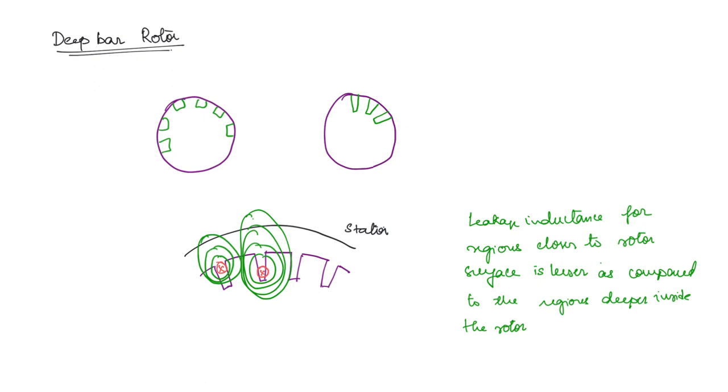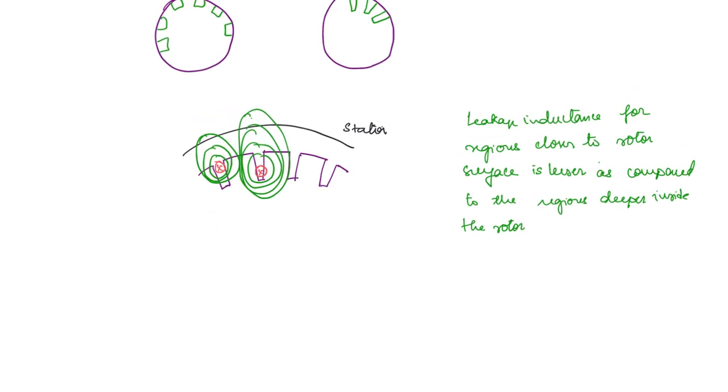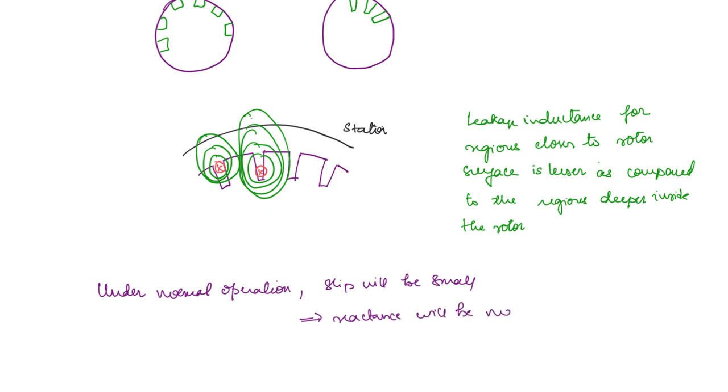So now what will happen? What is the effect of this on the torque? Under normal operating condition, what will happen? Under normal operation, slip will be small, right? And when the slip is small, the reactance will be negligible or much less compared to the resistance.